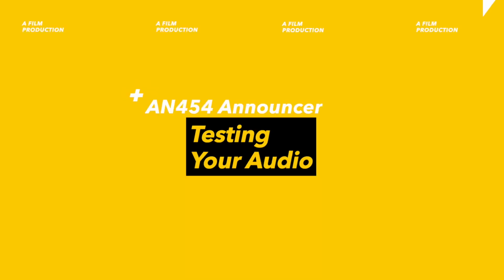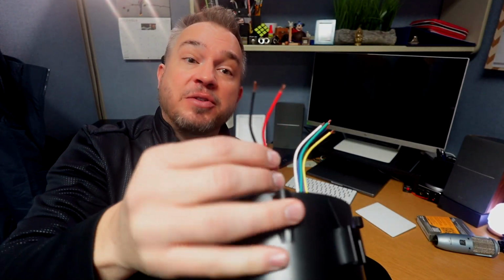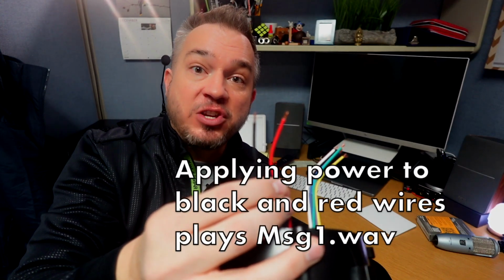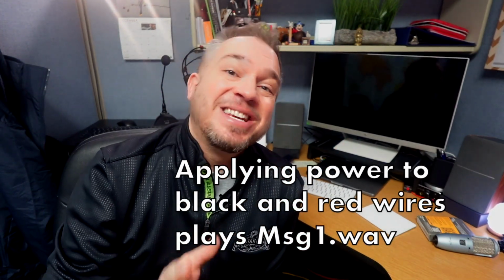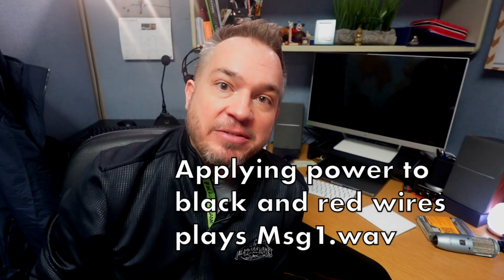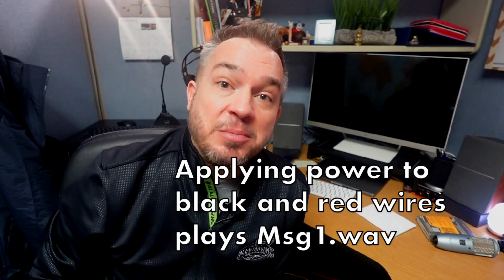Now it's time to test out your announcer before installation. Testing the announcer is simple. Just apply power to the black and red wires on the back of the unit. If you do that, you should hear the message that you saved as MSG1.wav. This means that your files were uploaded correctly.